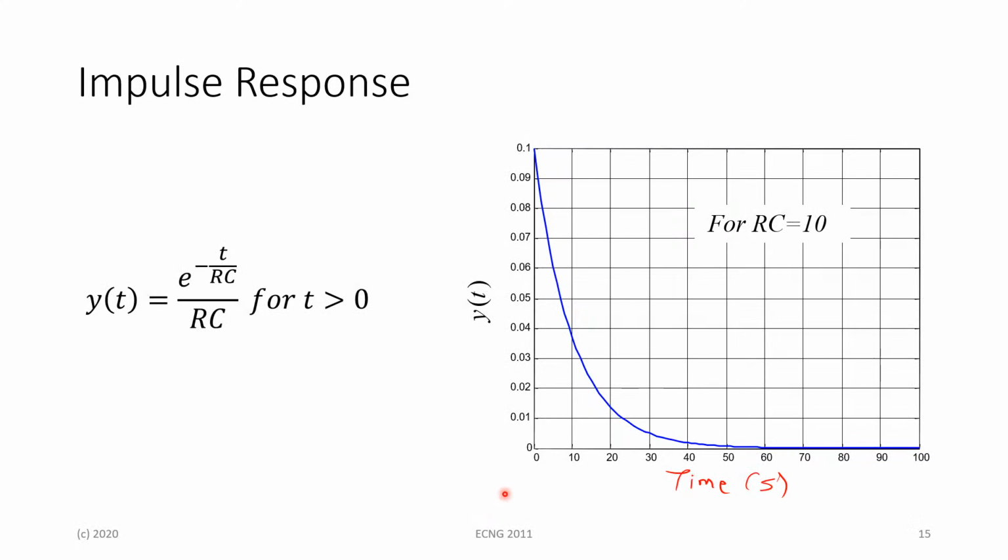Okay, right. So when we observe the step response and the impulse response, you realize that the step response gives us an indicator of how our system will respond towards some positive steady state value. And our impulse response is basically the opposite in this case, letting us see how our system can discharge from our initial condition.